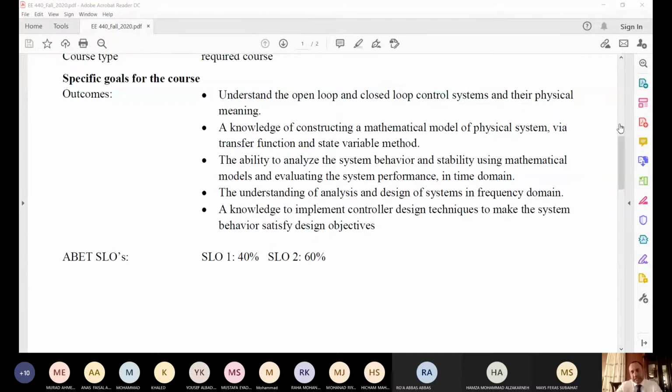After guaranteeing that my controller behaves as intended in a very good manner, I will go to the field, to the lab, to my workshop, whatever you call it, then I will implement my controller on the physical system. So in this case, at least I know that I will protect my system. The result will be somewhat close to the theory, but at the end of the day, I need to do some kind of fine tuning, because there's a mismatch between the physics and the math.